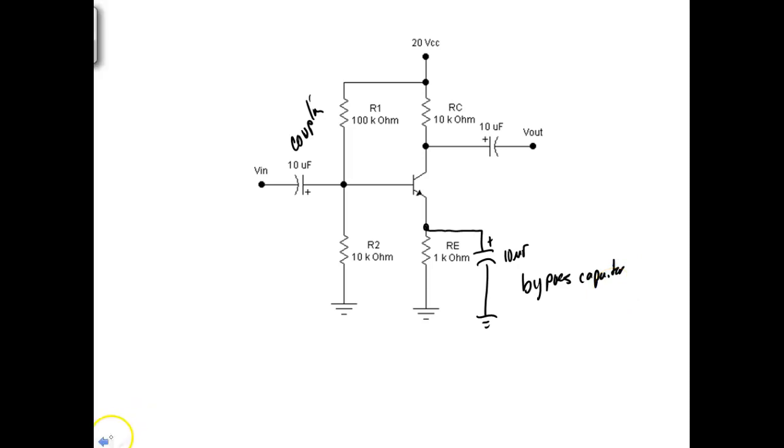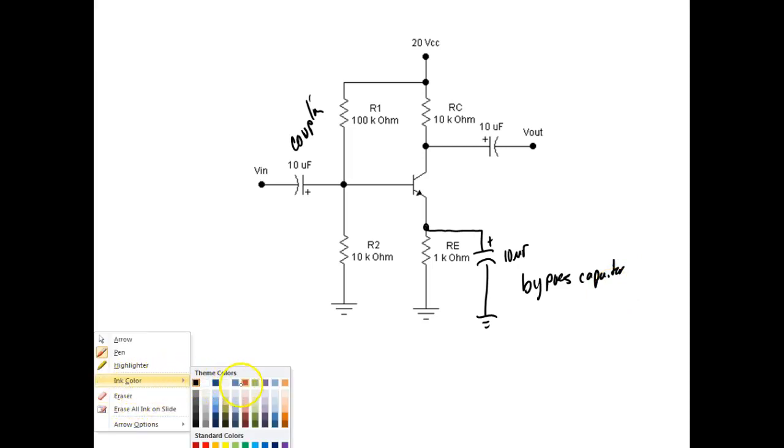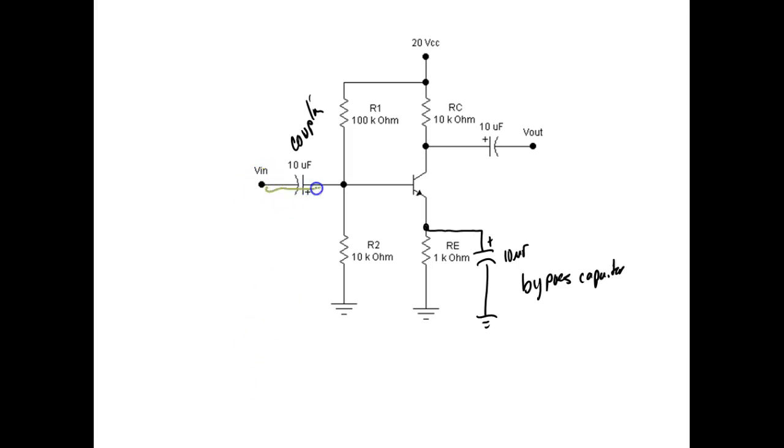Now what happens is my AC signal comes flying in. If I choose these capacitors right, my AC signal comes in, it goes that way, it goes this way, it comes over here, and does what? Now, it doesn't change your bias. It doesn't change your math as far as calculating your biases at all. The thing won't go into thermal runaway. But basically it causes the AC signal to bypass that emitter resistor.